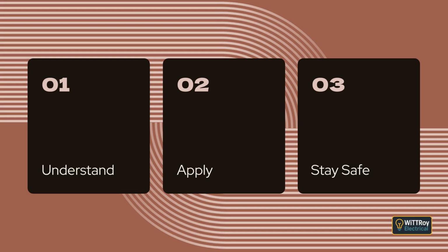Clause 2.9.6 Wiring. Wiring inside a switchboard must be installed so it can handle heat, magnetic effects, and movement from hinged panels. Conductors must be long enough so a panel can swing open or be removed without straining the terminals. Wiring must be fixed securely so it does not pull on equipment when the panel moves and so it does not press against devices behind the panel.